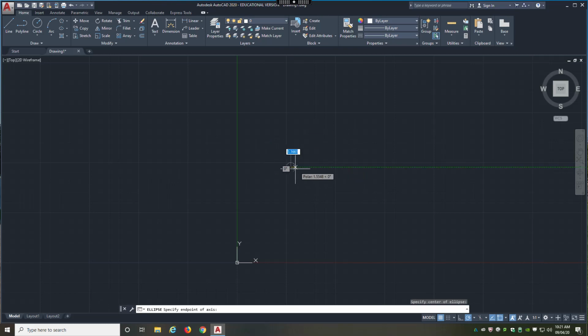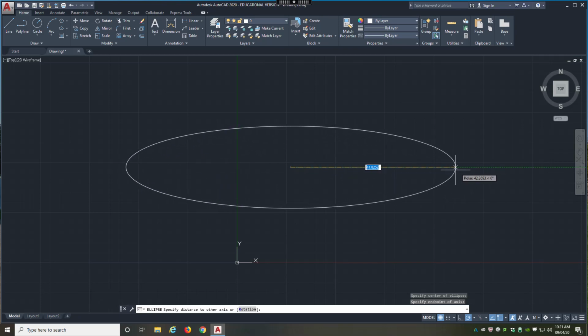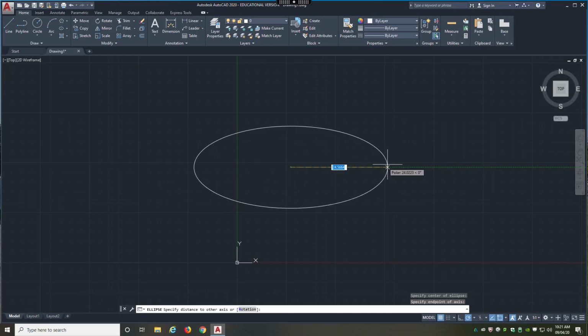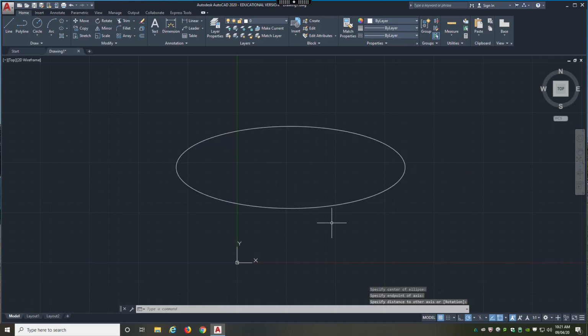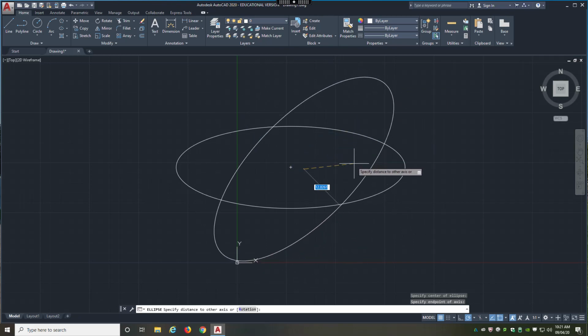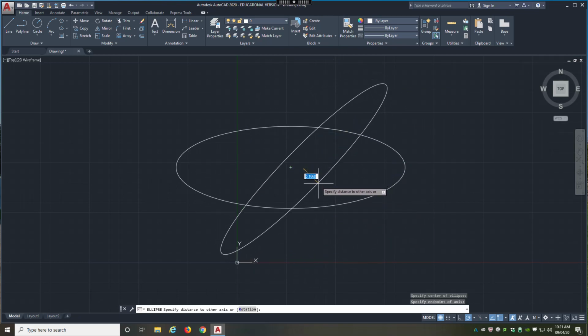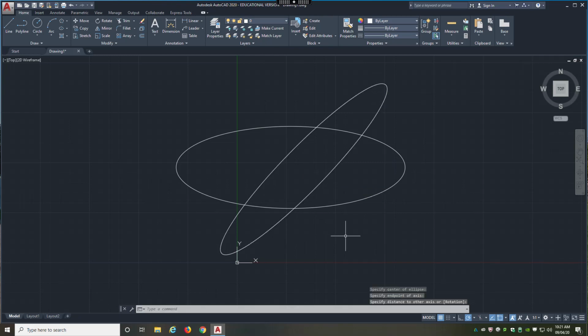And then you have 2 axes basically. So if I go on the y-axis, I'm going to left click, and then I specify my x-axis. You can see what's happening to this ellipse, and I'm going to left click there. So multiple clicks, and you can even do this on an angle if you wish. So there's my center point, and I'm going to say my first axis is going to be here, and my second axis will be perpendicular to that. So I'm going to left click there. And that's as easy as it gets working with ellipses.